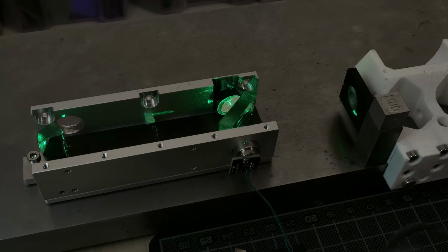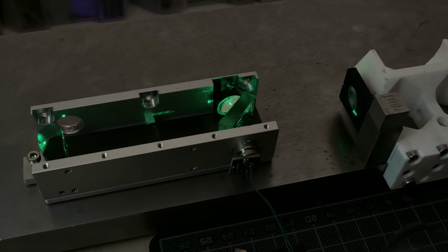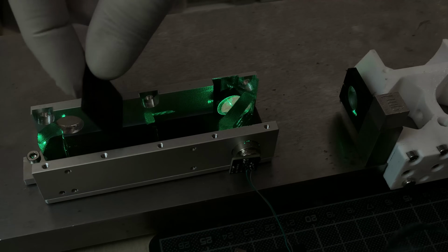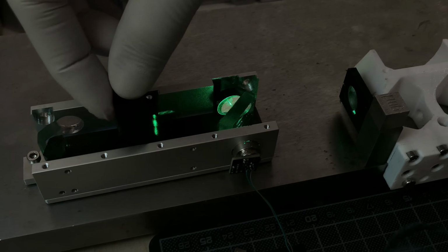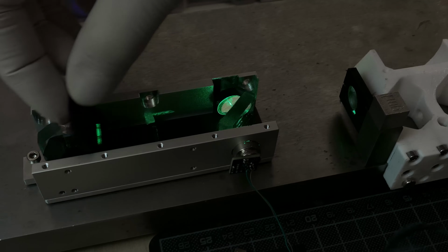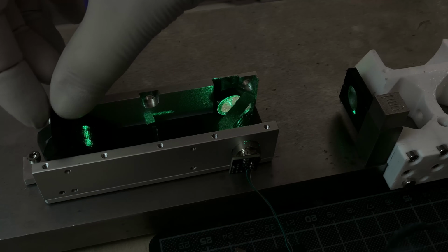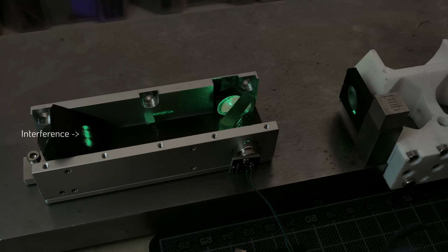First, let's take a look at the signal from the measurement arm. When pressing lightly against the sled, the path length changes and a brightness signal is produced through interference. Each blinking cycle corresponds to a length difference of about 250 nanometers. In future, 2 photodiodes will be placed at the location of the blinking spot.